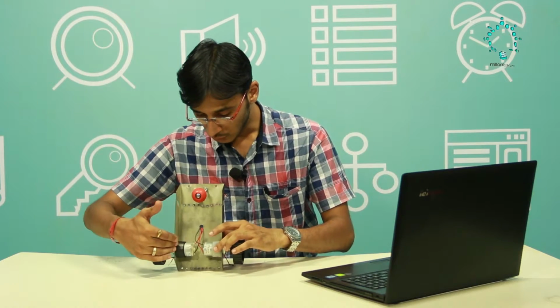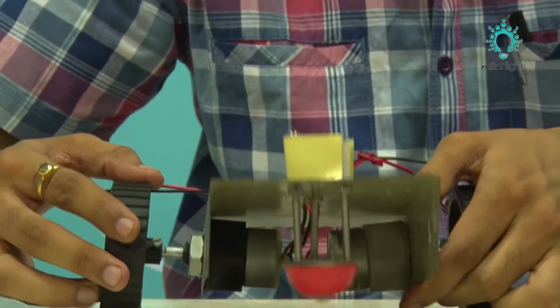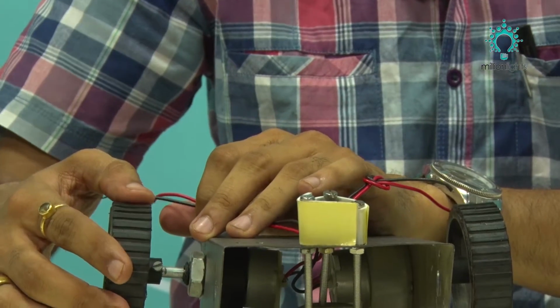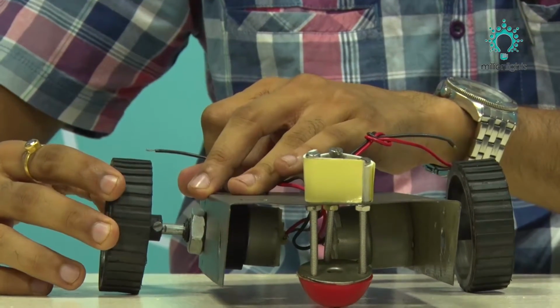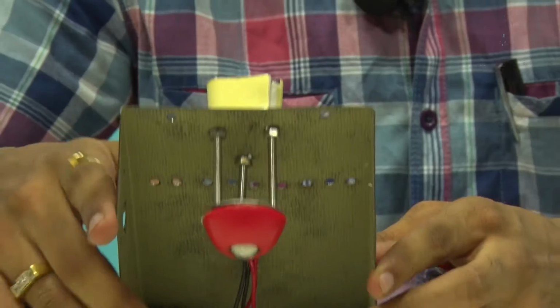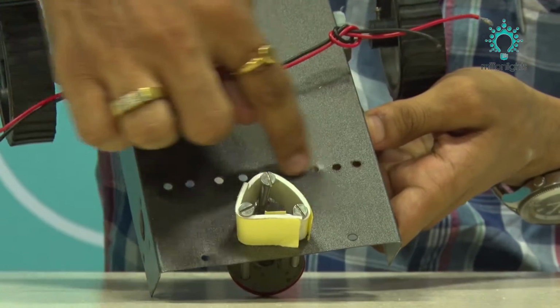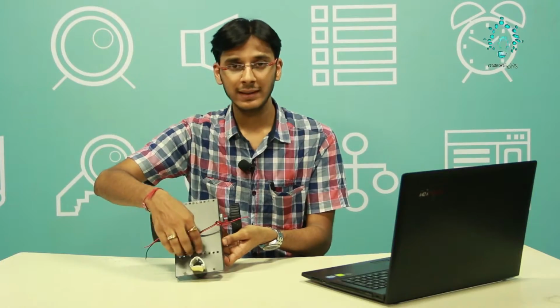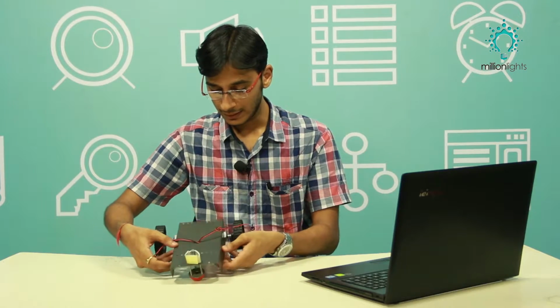Okay, so these are the two motors that I have fixed, and to the shaft of them I have connected these wheels, and for adjusting the wheels I have used this screw. So if you go to any robotic shop or any electronic shop, you will find the chassis, the wheels, the motors. You just have to connect them, and with the help of this screw you can tighten and fix them. So this is done, and then the caster wheel is also there, you can connect it. Now you will see that there are a lot of slots in here, so they are used for connecting sensors and all. We'll see that in the later part.